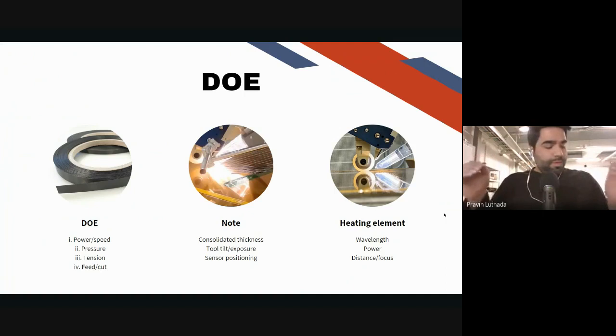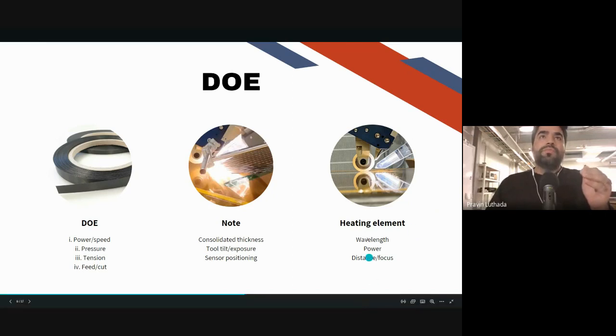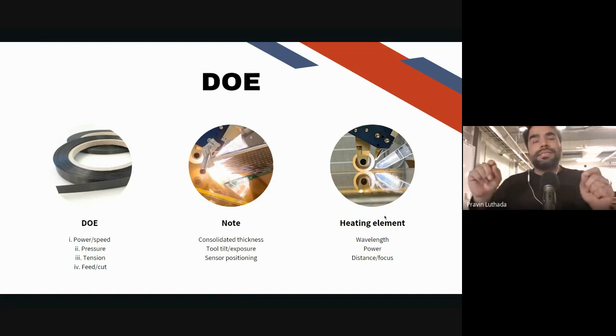And you would want to have all the different parameters. That is, you have a certain intensity of power, heat profile, and the speed that you start with, usually the lower end of it. And then you would want to change it successively to arrive at a better version that is more suitable and allowing you to see, oh, now I see some bonding happening. And then you would do that at different speeds.